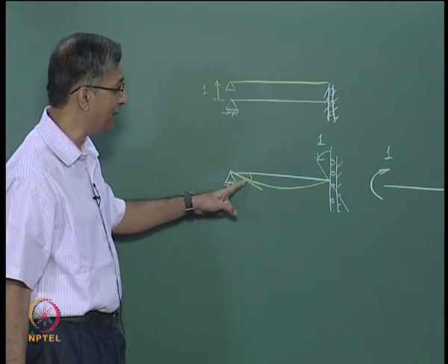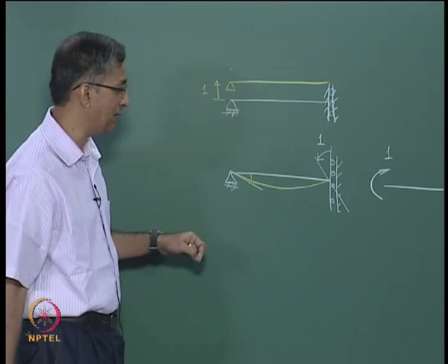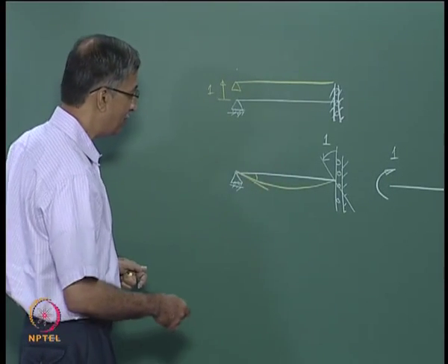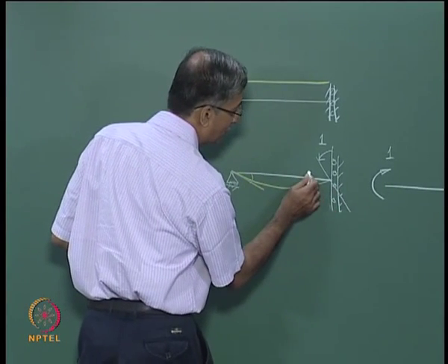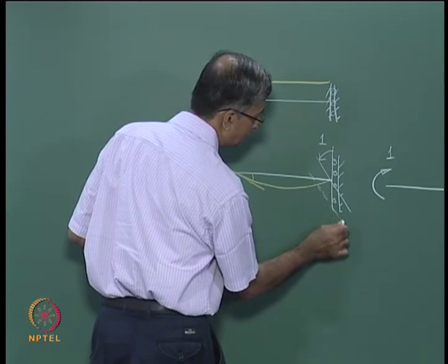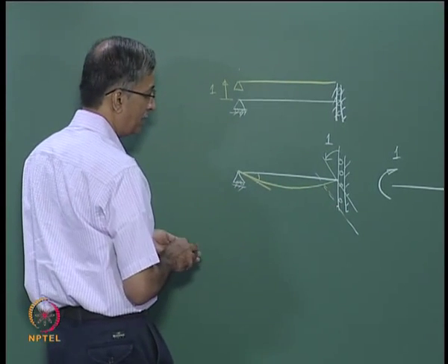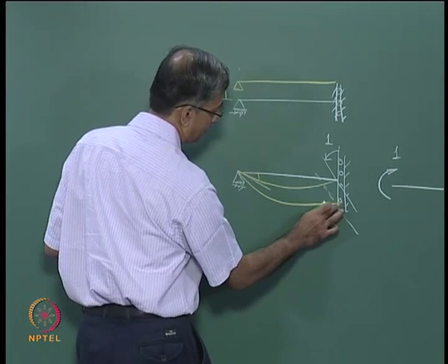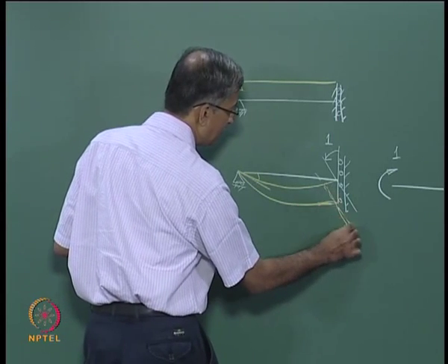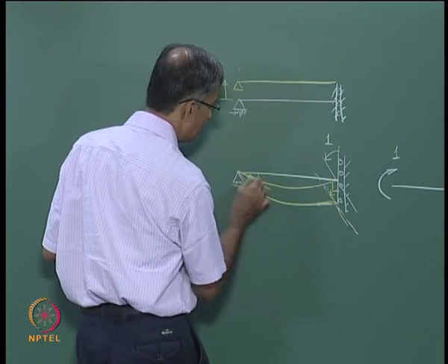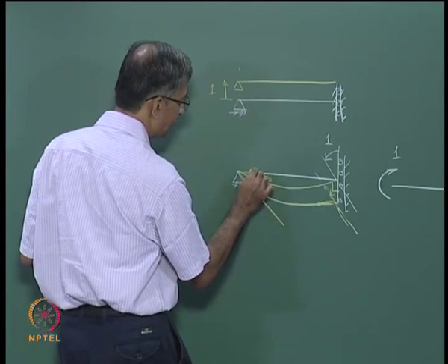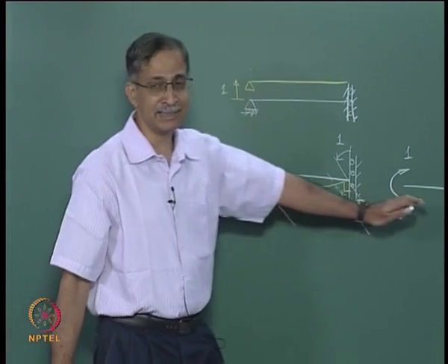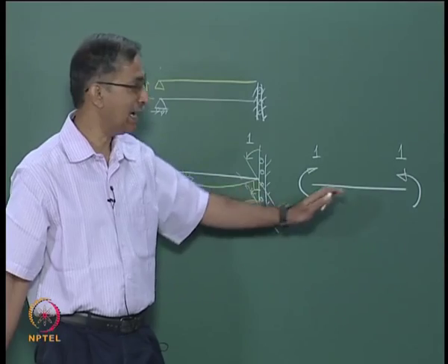It's certainly minus, but it's not -1/2, it's -1, which means this has to deflect some more, and that's not a problem. So let's say this goes down to a point there, you can get the desired deflection, still maintaining this change in angle is 1 here, and from half this increases to 1. So that's a physical explanation, and the answer is absolutely crystal clear, it has to be -1.